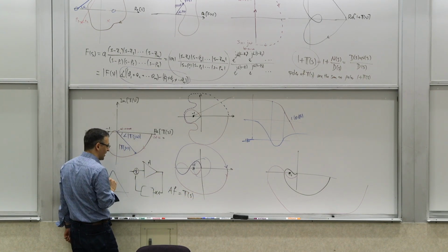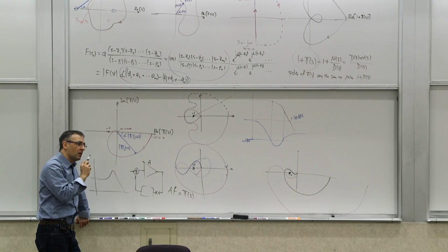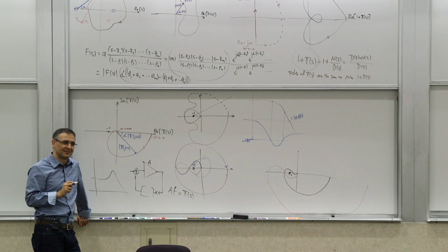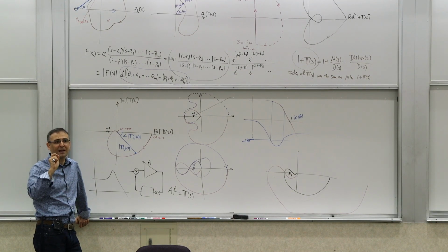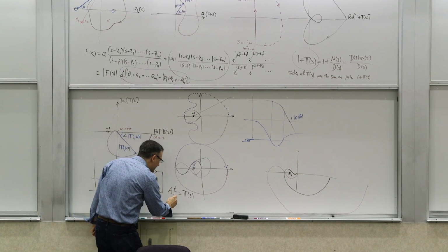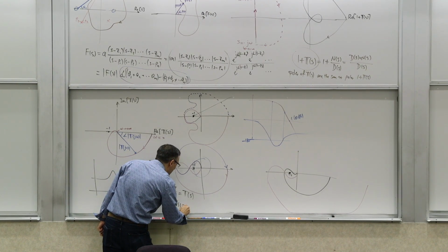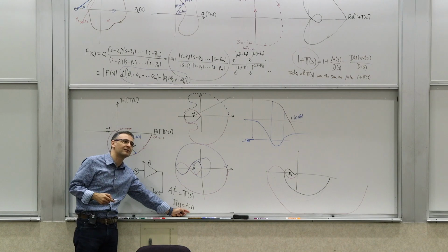But sometimes people say, especially in the case of op-amps, the worst case scenario is if I have a feedback of 1. Assuming that you don't have active feedback, say the maximum feedback I can apply is a wire that shorts the output to one of the inputs, to the negative. That's unity feedback. And you say, well, since that's the maximum amount of feedback I can apply, in that scenario this T of S becomes A of S. And that's why a lot of times, especially in the case of op-amps, people look at the open loop of A of S.